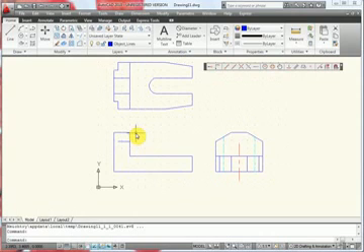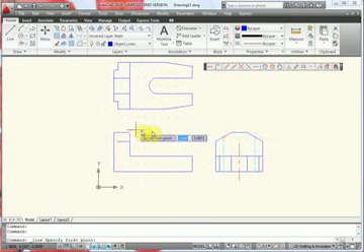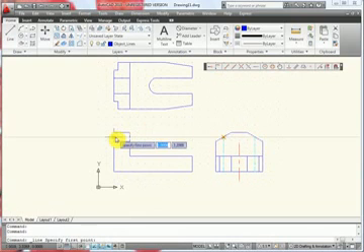And now I'm going to add another line. So use the line command. And I want to snap where this hidden line is, back to this line, intersection. If you have too many object tracking snaps located, it'll be hard to find. So to get rid of those, you just go over them again, and the object tracking will turn off for that particular snap you've made.